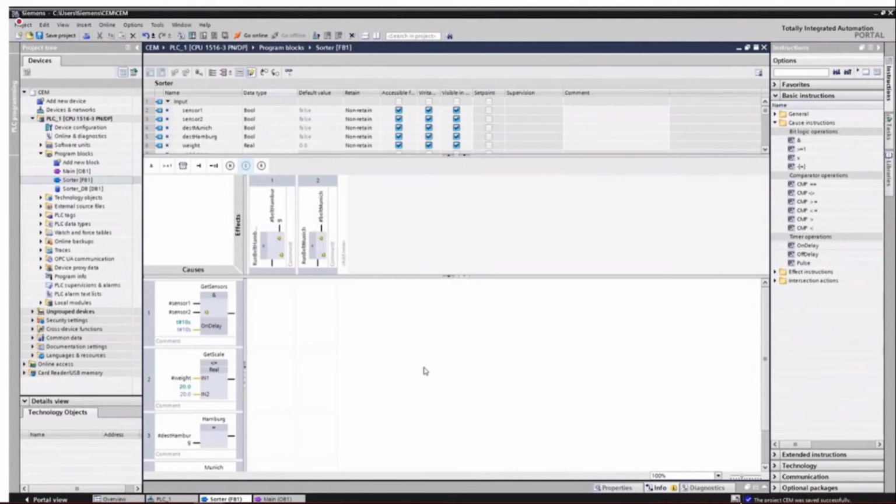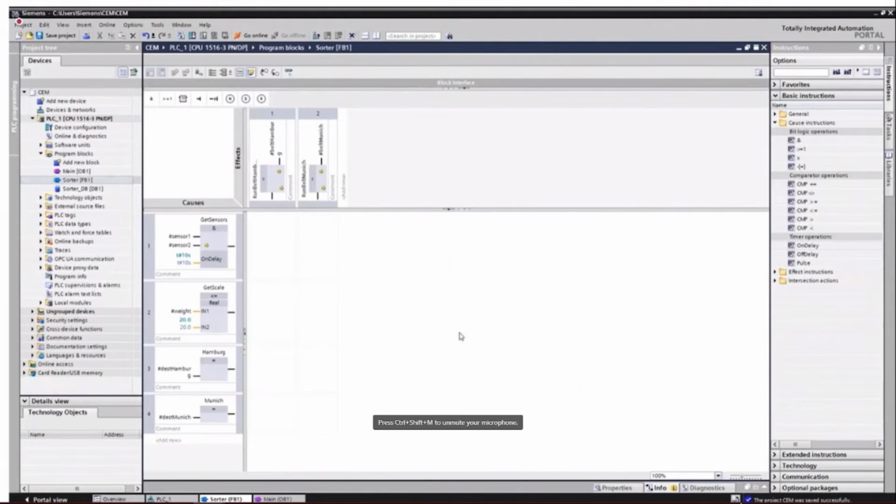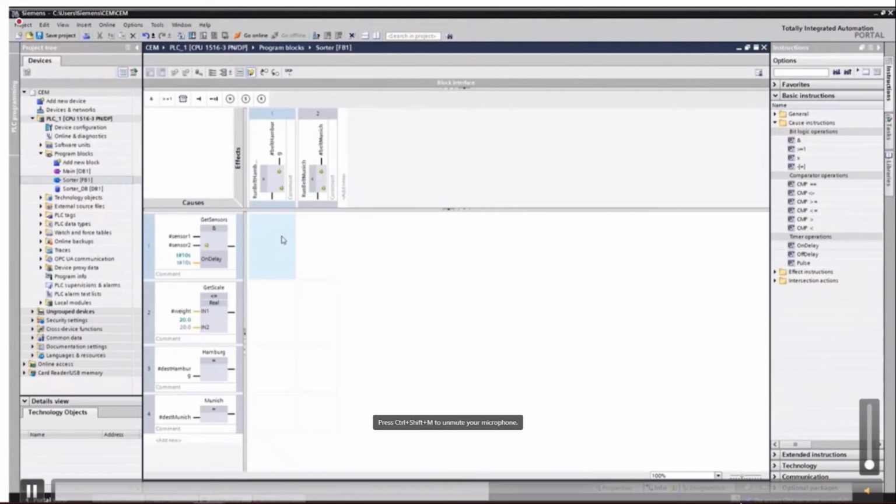Now we have to connect the matrix. So individually, what all logic will be connected to individual outputs. The first will be connected to both. So we can take an endpoint here and we can define. In this case, we have 3 out of 3 connectivity. So different connectivities can be defined in this cause effect matrix. I'll just make it a little bit fast.